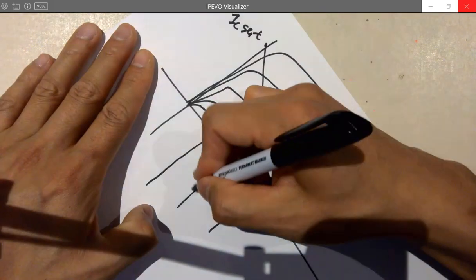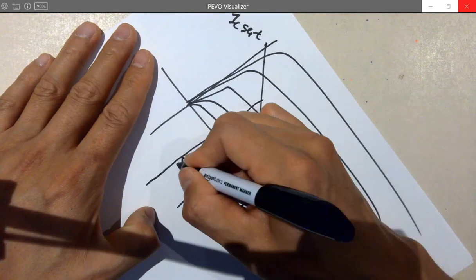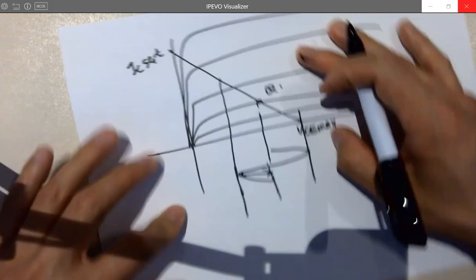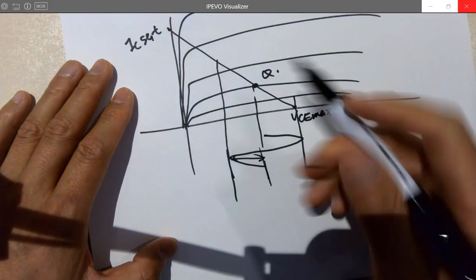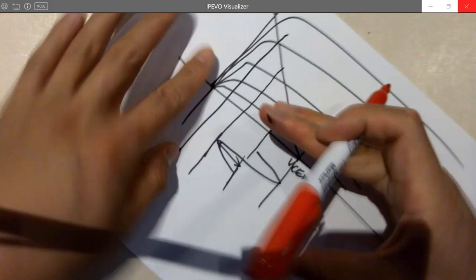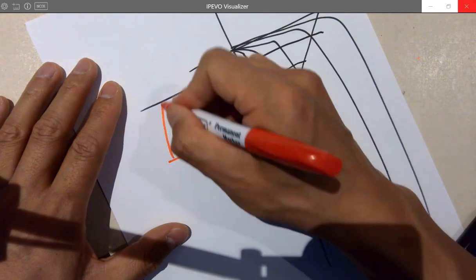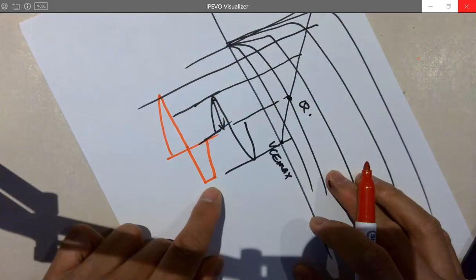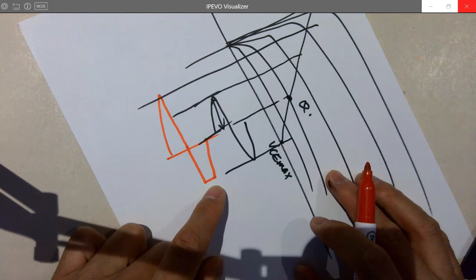Why? You just want to make the amplitude this as a maximum, because if you have a larger amplitude, then here you have a lot of space to swing, but here not. If you have a sine wave, you are going to see the bottom of the sine wave being clipped.